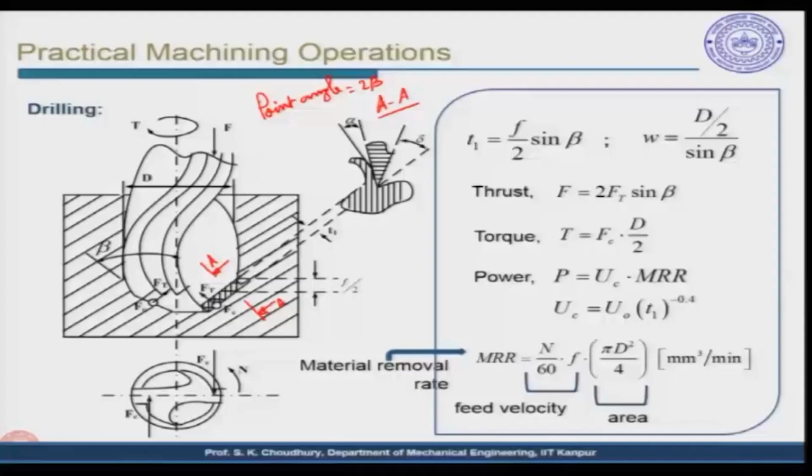If you see this diagram, here the torque is given and this is the force, which is the thrust F, both are given to the tool, which is the drill here. Now, if you take a cross section AA, we said that it could be visible like this. So, here we have the tool with the rake face, and this defines the inclination of the rake face of the tool. In this case the tool is the drill.